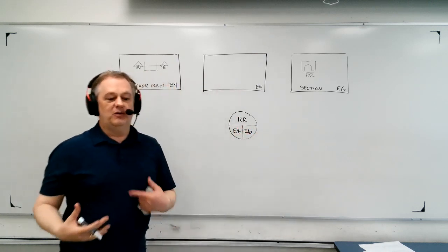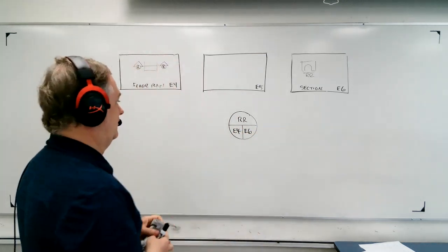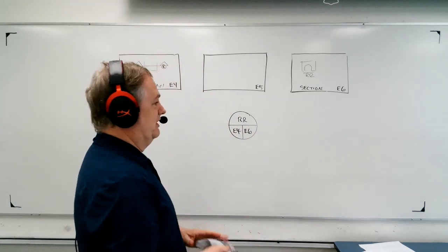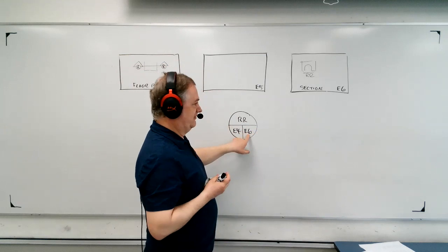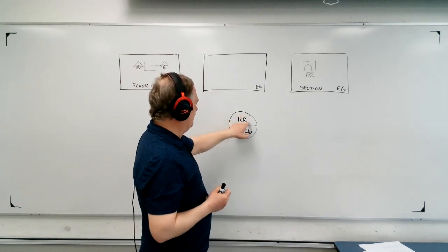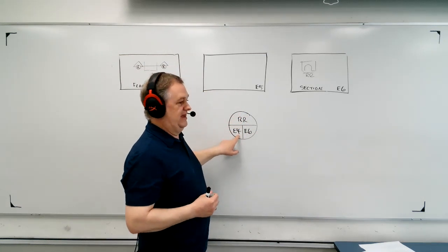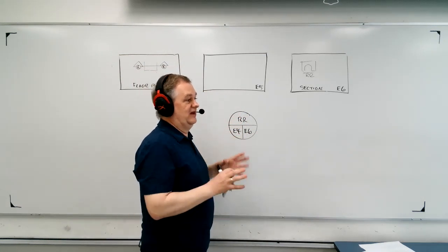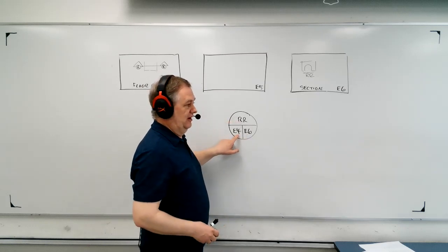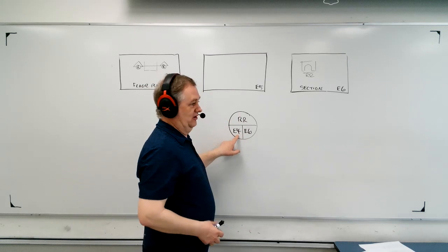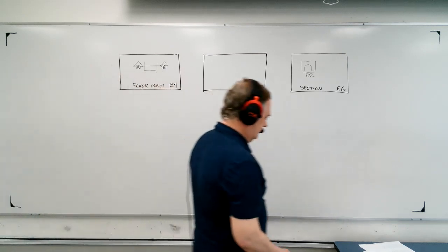And that's the way that you actually read these when you look at them. That's a standard that's followed quite closely. So if you're looking at a section, this is how you do it. This is the page that the section is on. This is the name of the section, and this is usually a floor plan where the actual reference was made. You can go look and find a section. This is where the actual object is shown. So that gives you a pretty good idea of the section reference symbol.